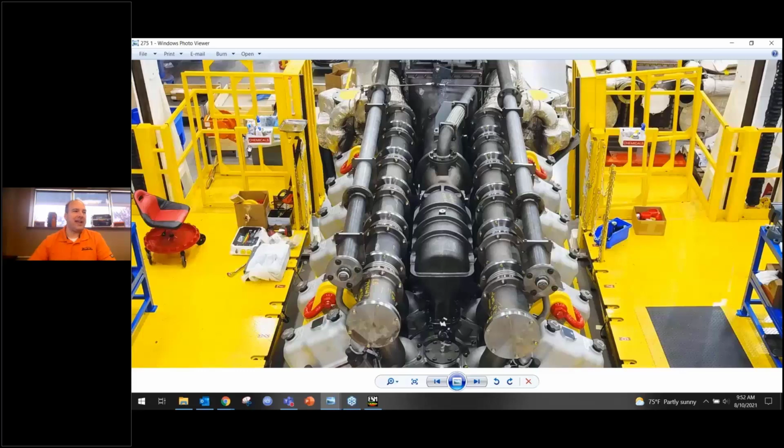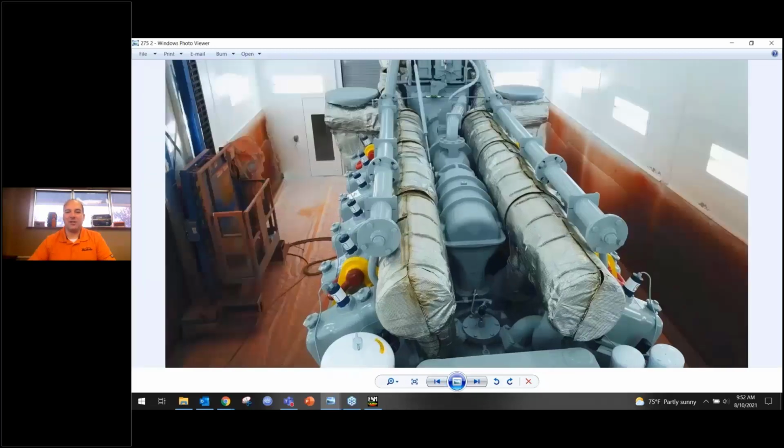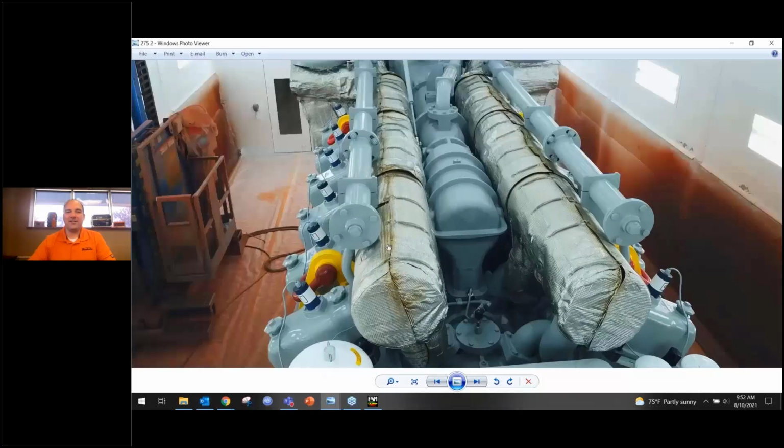As I look at it, one of the things that I see is there's no insulation around here. The 275 GL Plus switched from a liquid-cooled exhaust to an air-cooled exhaust. So as I go back and forth to my picture here, all of this stainless steel was removed, which is very important to carrying the heat away from our intake manifold.